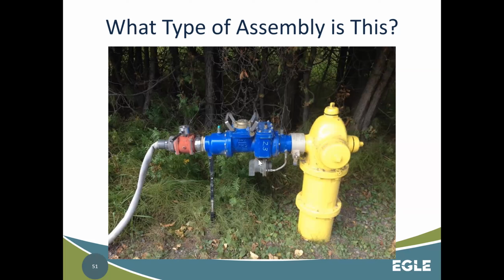It's a metered RPZ. Typically, if someone's going to fill off a hydrant, my guess is 99% of the cities out there have a requirement that they have to use a city-approved RPZ fill device off a hydrant. You should not just be letting anyone connect to your water system to fill off a hydrant without either proper permits or proper equipment or even supervision sometimes, okay?